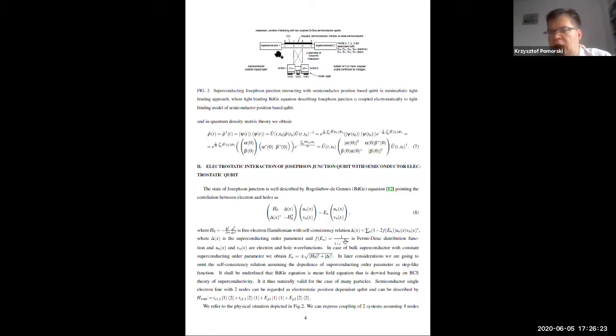So essentially, a superconducting Josephson junction is nothing else than superconductor, insulator, superconductor. This could also be a tunneling junction, or it can be a so-called weak link. In case of a weak link, we can have a superconducting material, a normal, non-superconducting metal, and again a superconducting material, or we can have a strong superconductor, weak superconductor, strong superconductor.